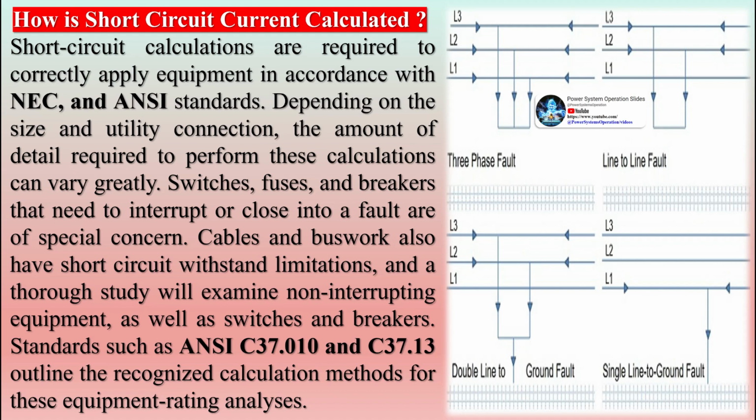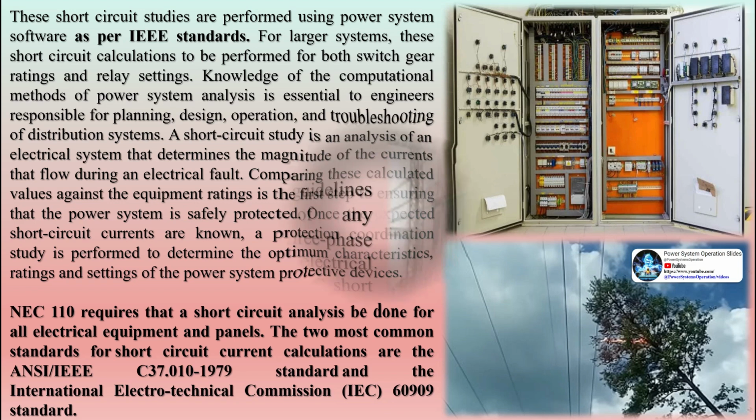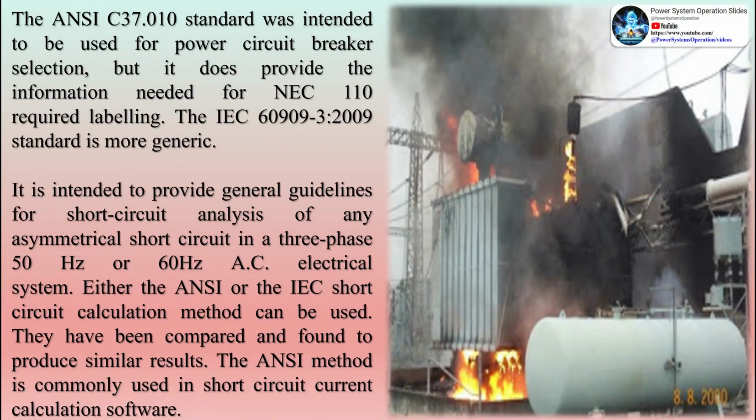For example, larger hydroelectric power stations tend to be synchronous machines. Inverter-based renewables contribute very little SCL, reducing the strength and therefore stability of electricity grids, which means the ability of these grids to withstand faults is reduced. Ultimately, the ability to add more inverter-based technologies to the grid will become constrained by the need to maintain grid strength. Transmission network protection systems rely on the short-circuit level to detect faults and know when to operate.